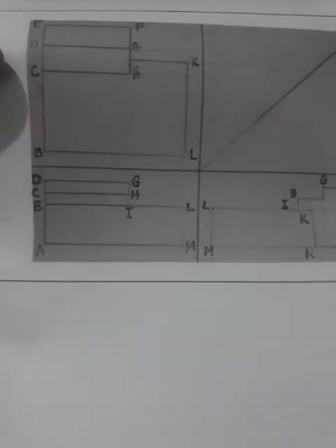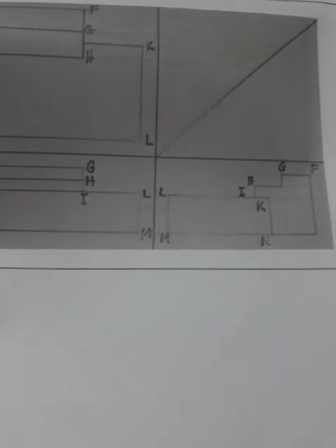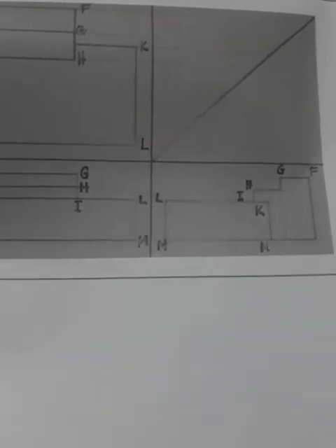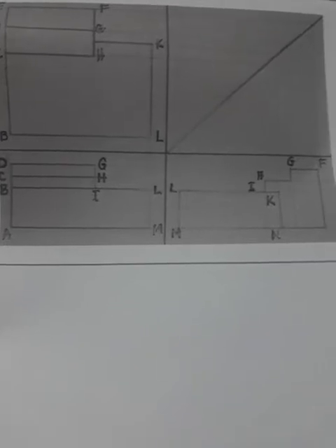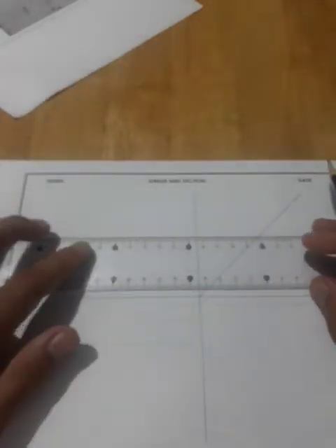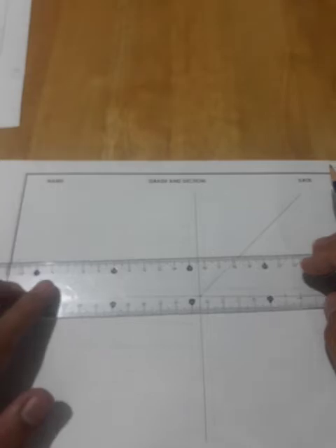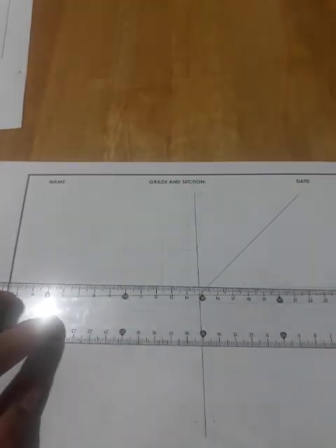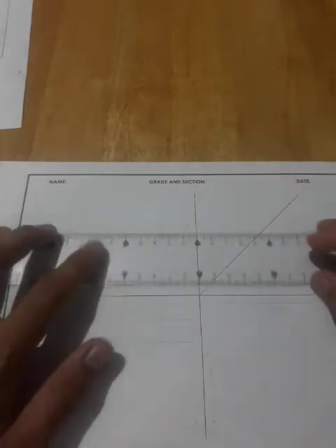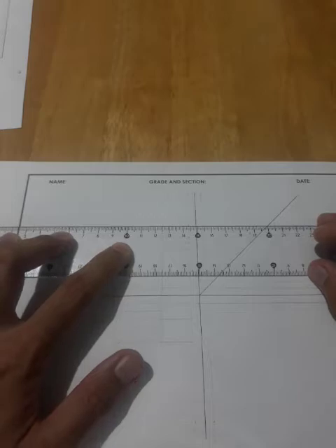Please, no, if you measure accurately the top view and front view a while ago, you will just simply project the lines carefully using the miter line and of course your lightest pencil. So let's try. So first, project point F. This will be point F, and then I want you to project the lines up to the miter line. Okay?